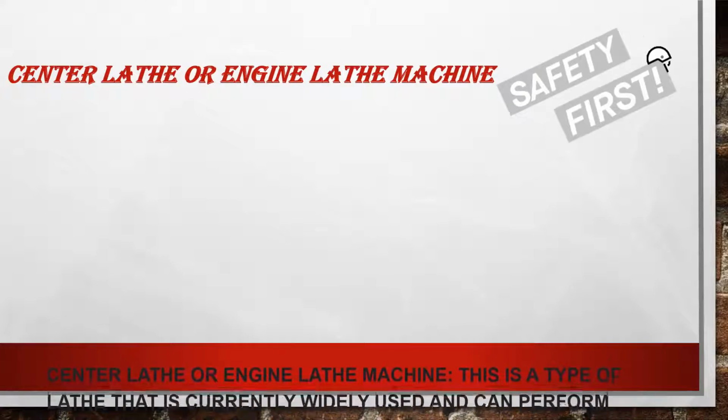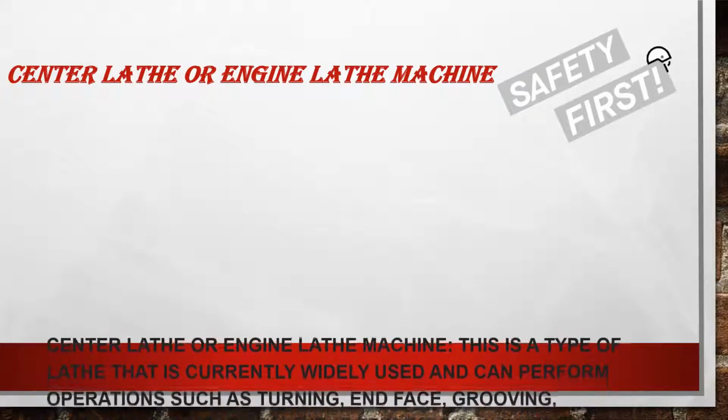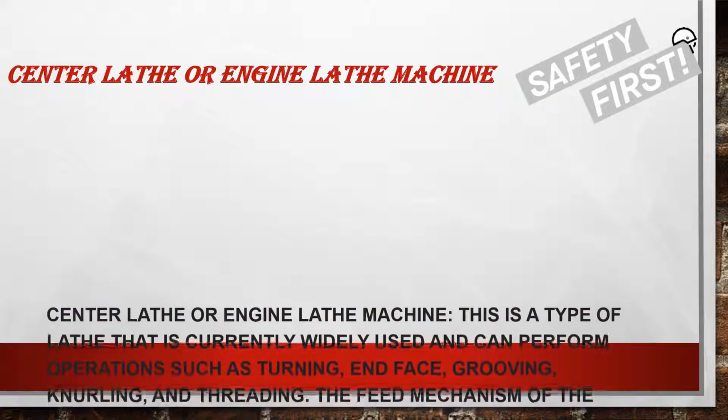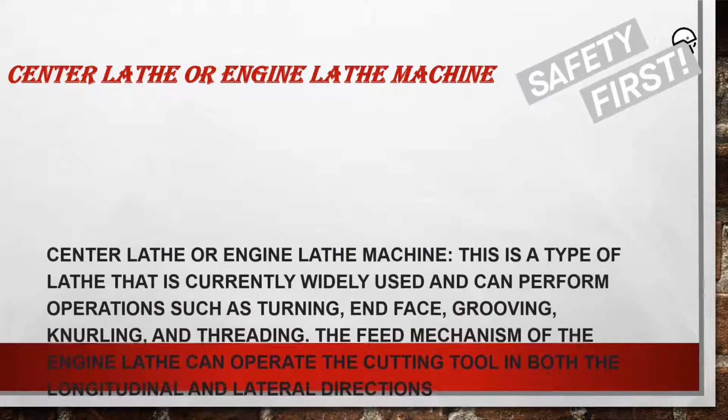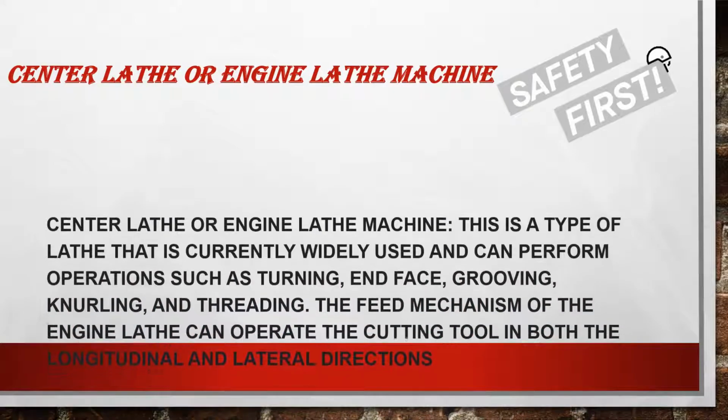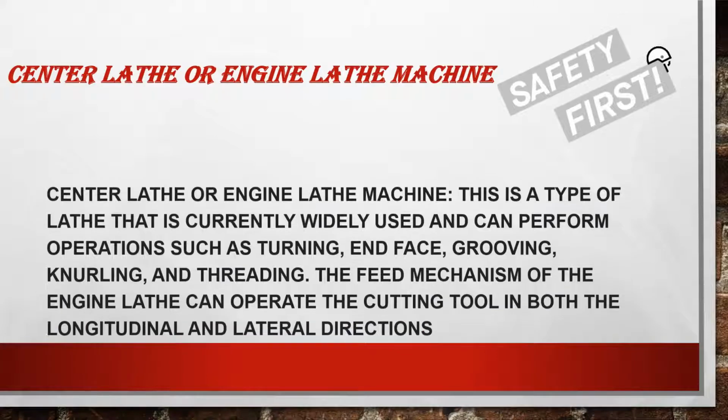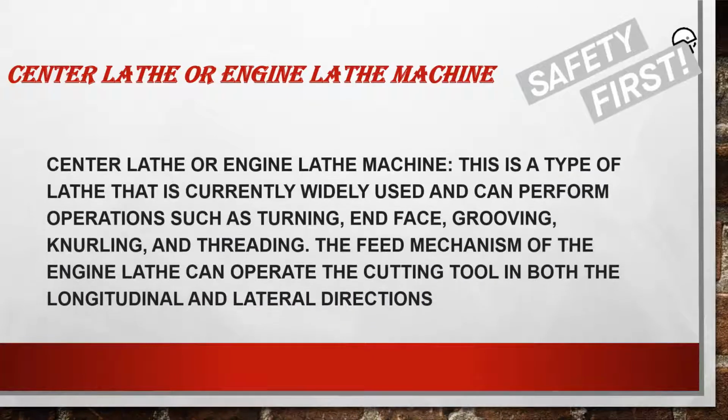This is a type of lathe that is currently widely used and can perform operations such as turning, end face, grooving, knurling, and threading. The feed mechanism of the engine lathe can operate the cutting tool in both the longitudinal and lateral directions. Speed lathe machine.